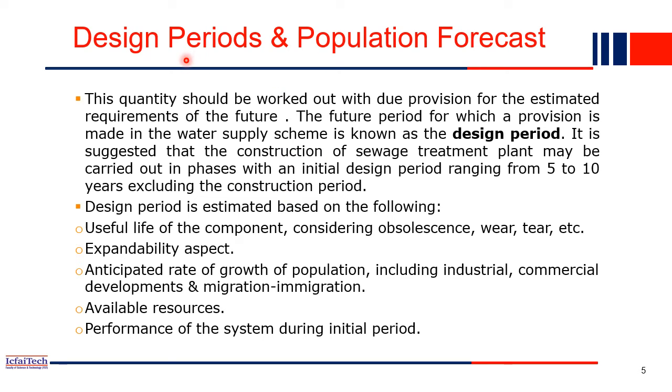And the design period, we understand that is the future provision for which the water supply scheme is designed. After the next 20 years or 30 years, for that we are designing the entire treatment plant, that we call the design period. So it is suggested that the construction of the sewage treatment plant may be carried out in phases, right? At the initial design, maybe 5 to 10 years.